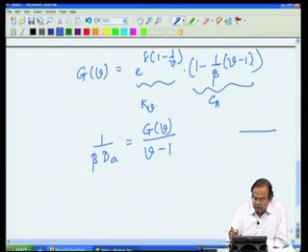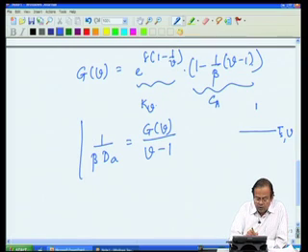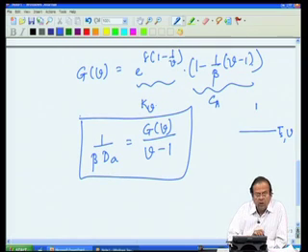We have a catalyst surface, temperature here is Ts, or in terms of dimensionless quantity V, and the bulk condition is 1. Basically what we did was, we wrote mass balance, we wrote energy balance, defined dimensionless quantities, and put all these things together. Finally, we ended up with a single equation in terms of dimensionless temperature.